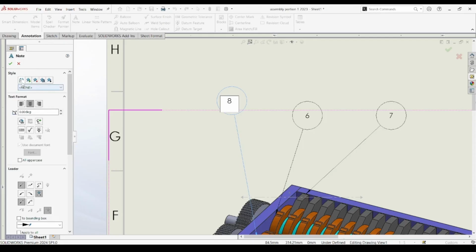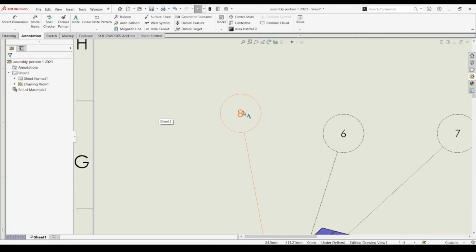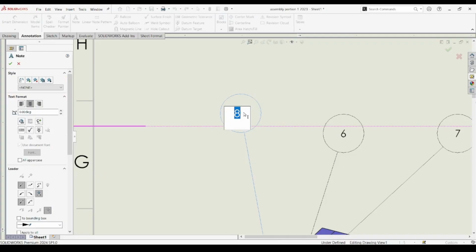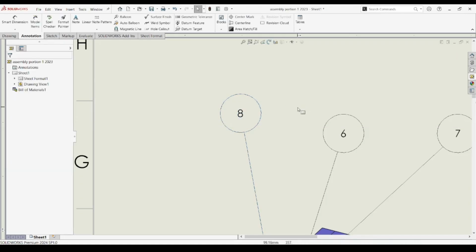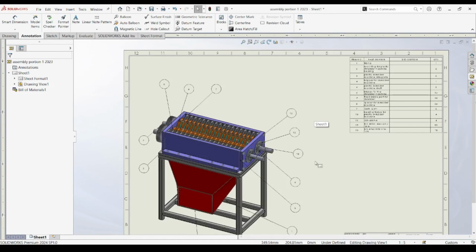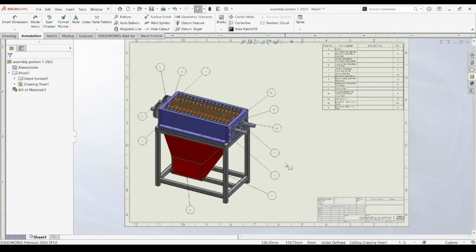Additionally, we explore how to handle suppressed components. Sometimes, parts like temporary supports, reference geometry, or optional hardware are present in the assembly but not meant for the final build. SolidWorks gives you control to exclude these from the BOM without deleting them from the model. This keeps the design workspace intact while ensuring the BOM remains clean, accurate, and production-ready.